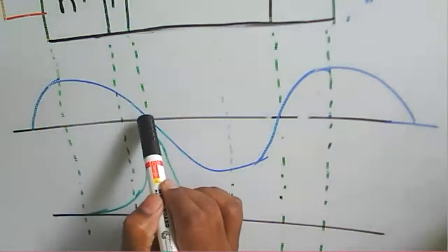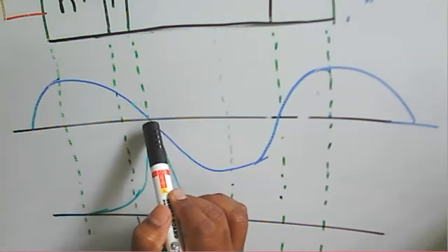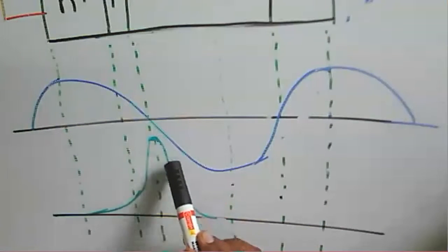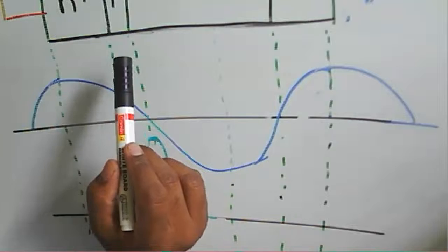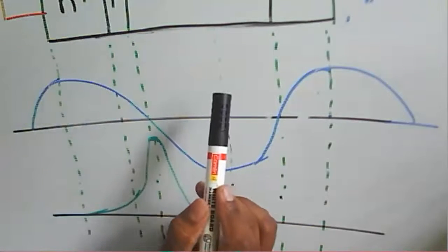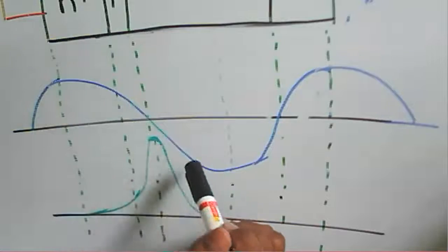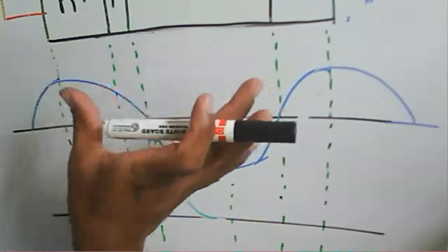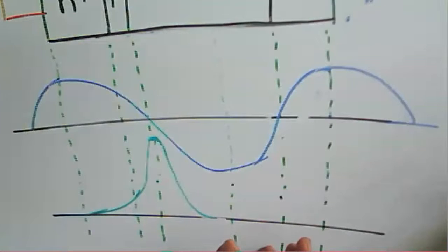So up to the positive half cycle, there will be an exponential increase in the current. Then the current decreases. At the negative half cycle, the current decreases because the avalanche multiplication stops, as the voltage across this particular diode drops compared to the breakdown voltage.